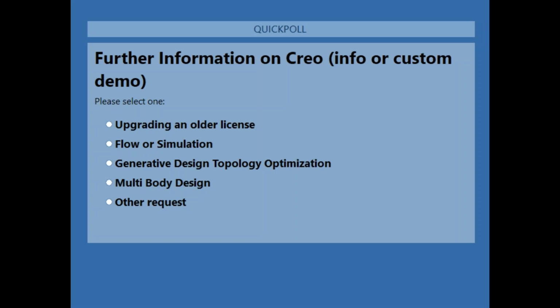Cool. Next question was, what level of computing power was used for the live analysis? Yeah, so for the CSL, I guess the thing to touch on there is that with CSL, there's no CPU requirement. It just runs whatever your normal recommended CPU requirements for Creo. It's the same thing, but it does require the use of an NVIDIA CUDA enabled graphics card.